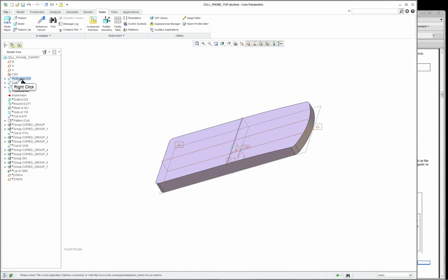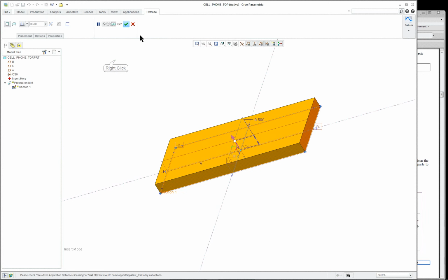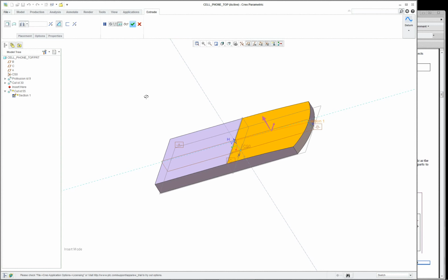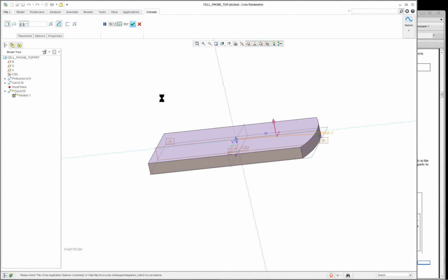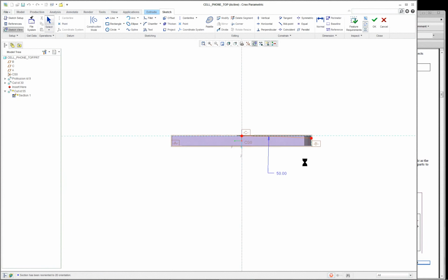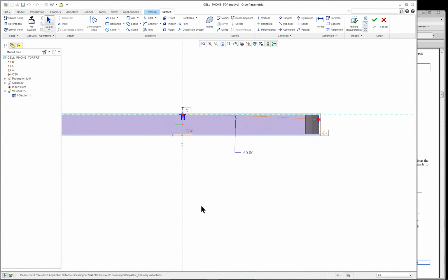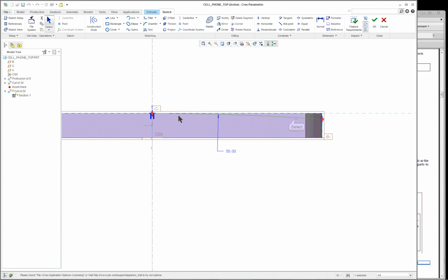Let's see if we can do that. Add taper. So you could have added a taper there. Combined all of that. This cut here, though, this is important. It's obviously going to be separate. And let's look at how they did the sketch on this. So this 50-inch dimension obviously is along this datum. And it has a very small arc to it because it's so large.